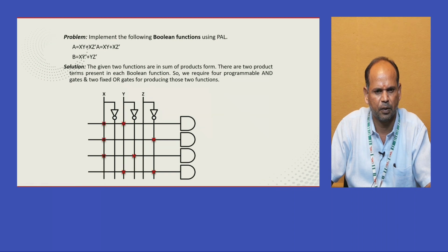That is, here initially the AND gate should be programmable with the intact fuses, that is the star marks, based on the given expression. For example, here they have given A equal to xy. So wherever the X and Y buffer inputs are there, we need to indicate with the star marks. That is intact fuse. Means that is the programmable AND gate.